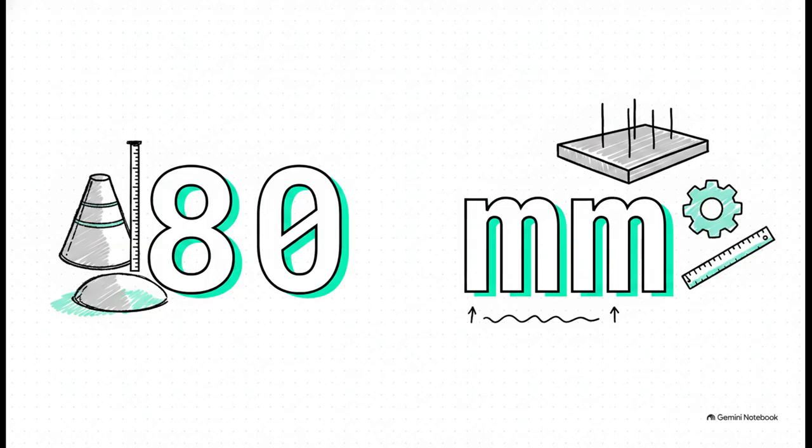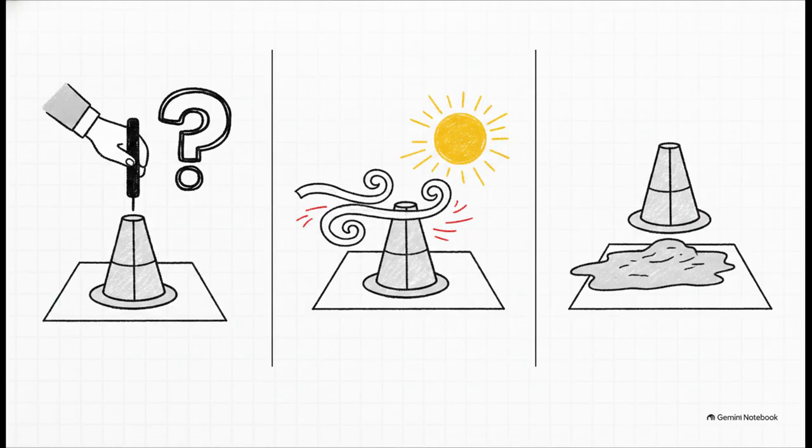We just subtract the slumped concrete height, which is 220 millimeters, from the cone's original height of 300 millimeters. This 80 millimeter true slump tells us we have a medium workability mix, which is honestly perfectly balanced for general construction work. Real quick, before we move on, let's lock in these slump test limitations for your finals.